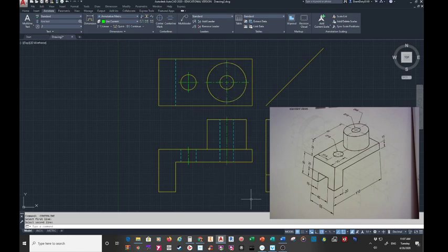Okay, so this one's almost done. Let's work on our 3rd view. So like I said, we're going to do the right side view. I showed you earlier, there's a little notch in here, and it's 20 up. And it is 15 over, looks like, and then 40 to the next spot. They're actually measuring from the back, which is here, but I think it's supposed to be centered, so let's see how it works out.